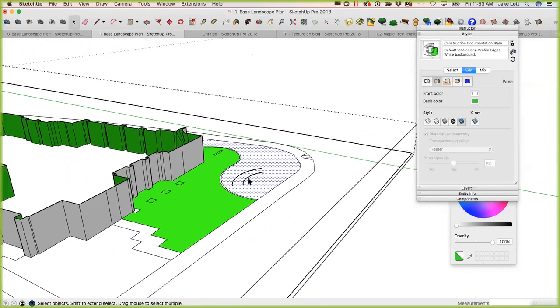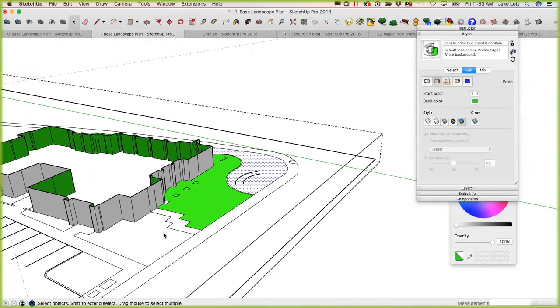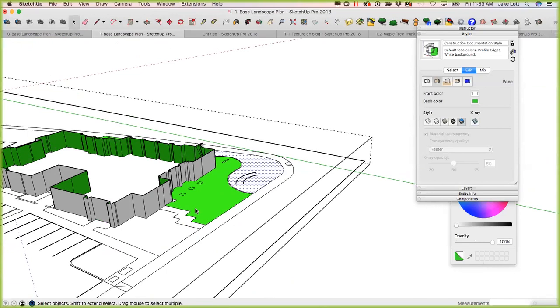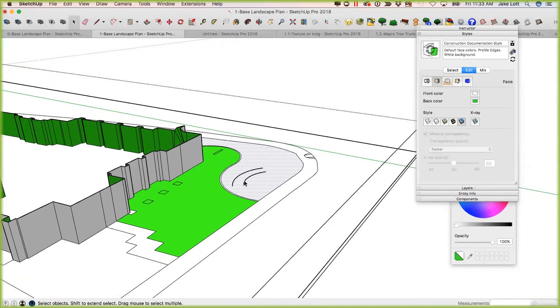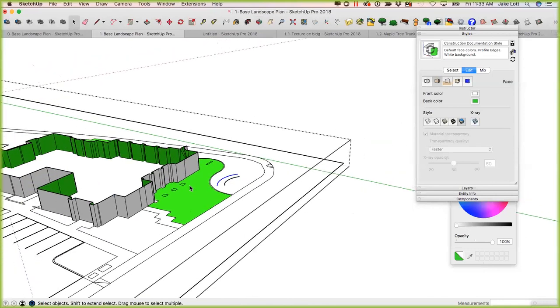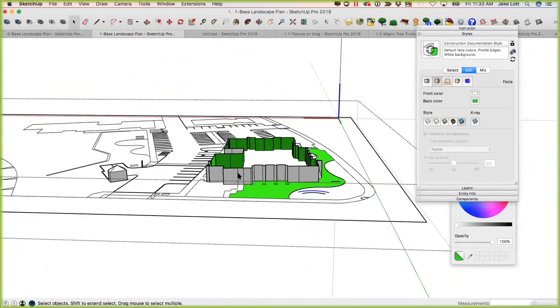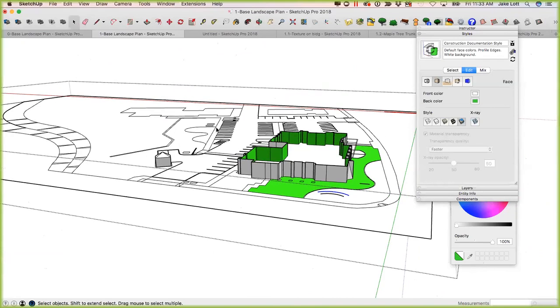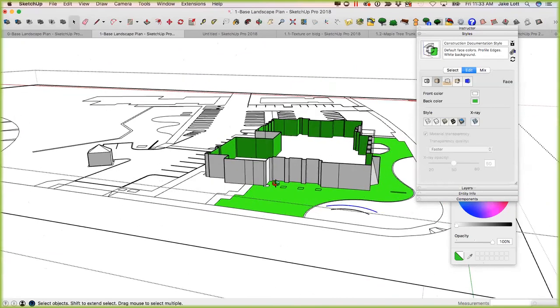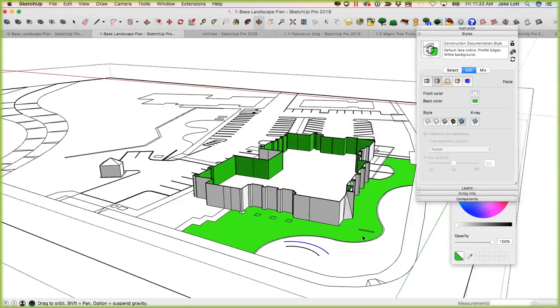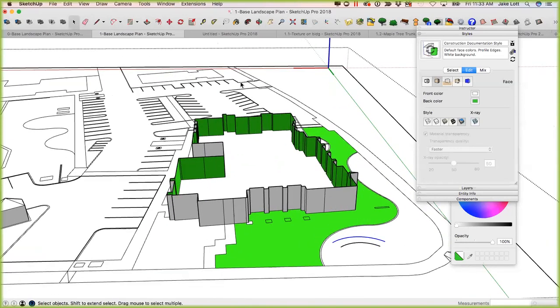If it's a true arc, if I just grab, and let's just place this arc here, an arc will offset. So again, it might look like an arc, but it might be line segments. That's definitely something that you have to be sure of, how it was drawn. And then again, if the shape doesn't allow the offset, it'll tell you that it just won't work. Obviously, it has to be within the raw geometry itself, not within a group, to be able to offset as well. So we're going to move right along.